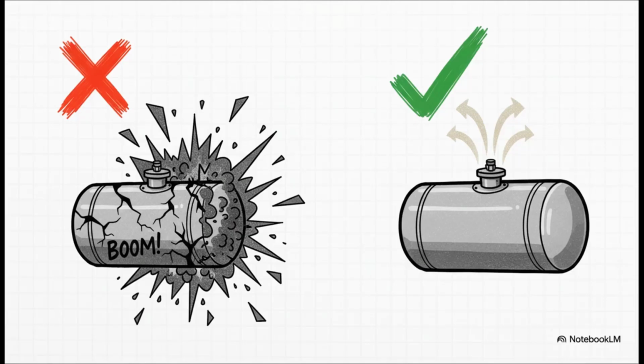If things go sideways and the pressure inside a tank starts climbing and climbing, these valves pop open all by themselves and let that pressure out safely. They are literally the thing that stops a tank from becoming a bomb. And in the US, it's not optional. It's the law. Anything over 3 psig, you have to have one, period.